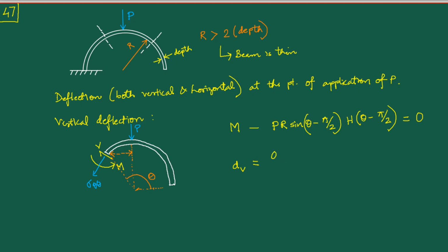So what I'm doing here is del U del P, and the U, as before, the strain energy, that is very much M squared by twice EI.